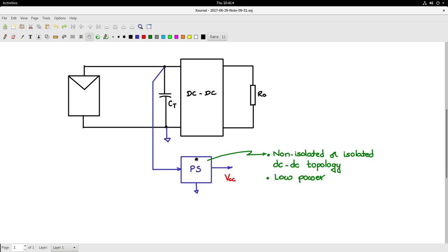In such a case, one may also consider taking power from the output side if the output voltage is lower than the terminals of the PV source. So if the output voltage is lower, then you have a lower step down ratio to obtain the VCC, which will power up the microcontrollers and the MPPT controller boards, and also the gate drive circuit.